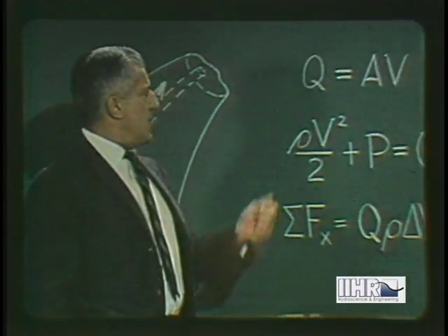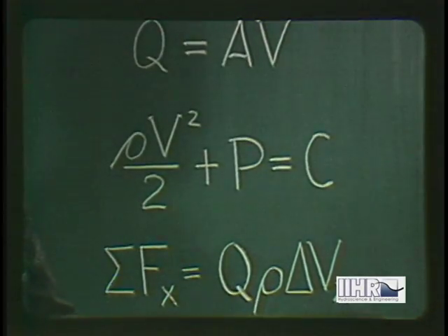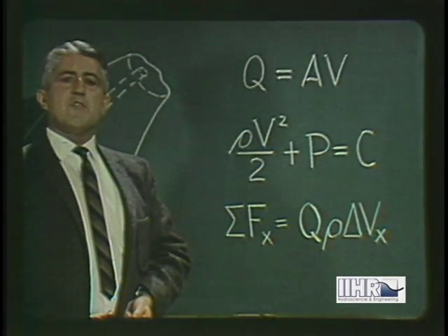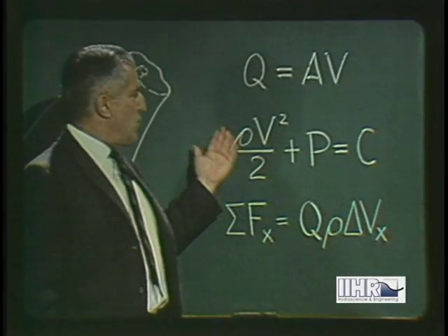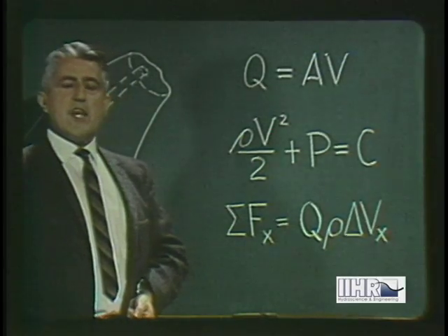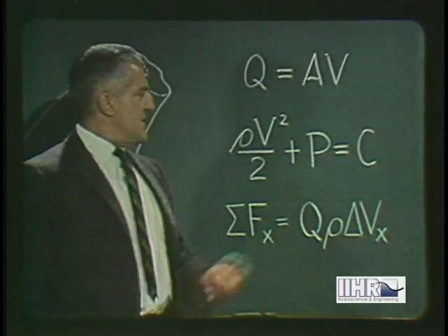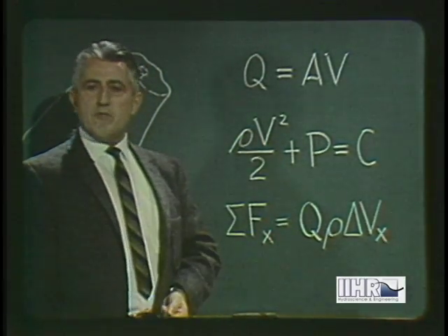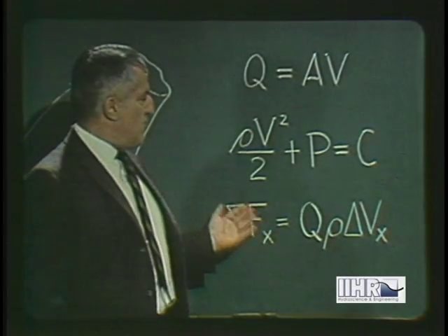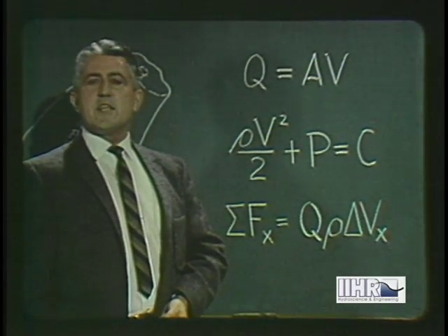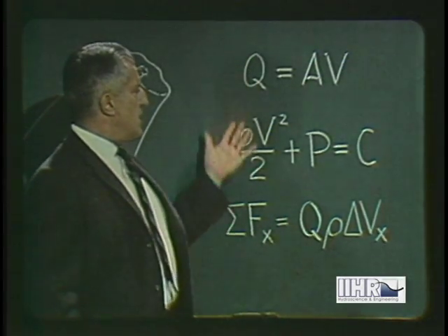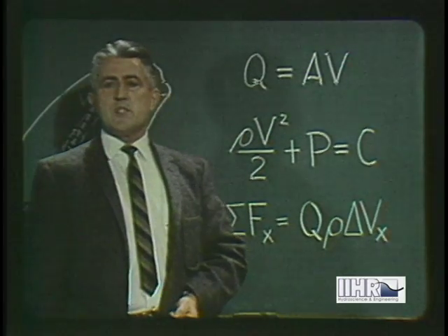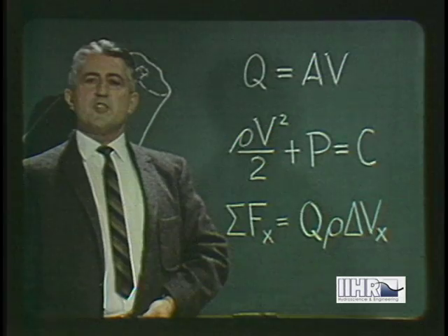The integrated equation of continuity is much the same as before, except that now the velocity represents the average over the entire flow section. The integrated equations of acceleration take either of two forms, depending upon the manner of derivation. One form, the work-energy equation, is very similar to the pressure-velocity relationship used in connection with the flow net, except that now the pressure, as well as the velocity, refers to the entire flow section. The other form, the impulse-momentum equation, is basically different in that it represents a vector rather than a scalar relationship. These three equations are thus essentially independent tools, which hence can be used in combination in the solution of problems.